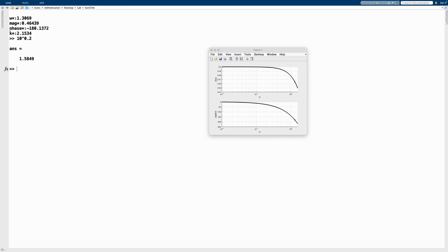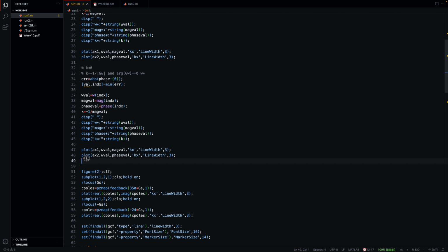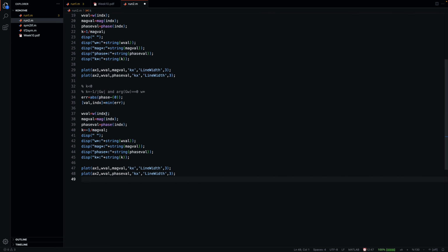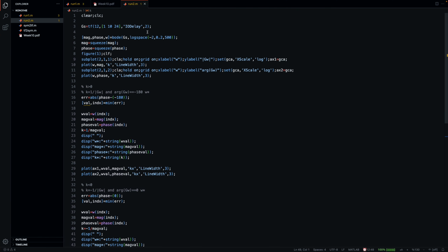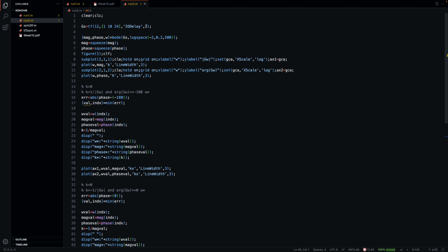And we can see that the gain value is 2.15. So let us basically copy the second part here. There we go. Yeah, that should be it. And we can see now the stability interval is between -2 and 2.15, and that's probably way less than the original system, which wouldn't have 2 seconds of delay here. So yeah, the stability interval shrinks if you add more and more delay to it.